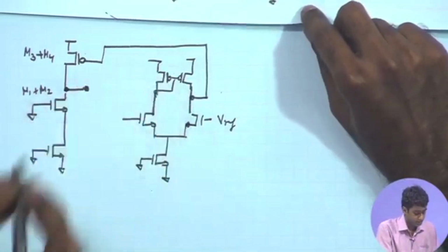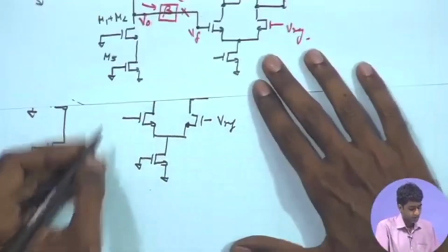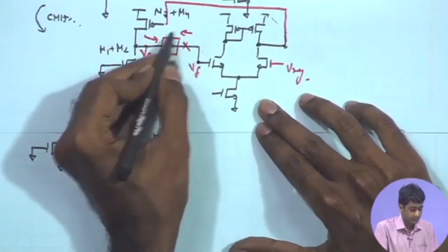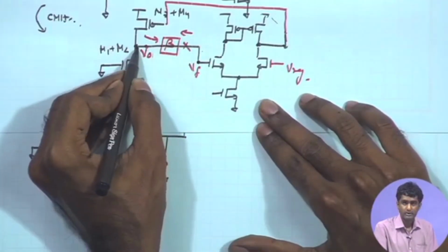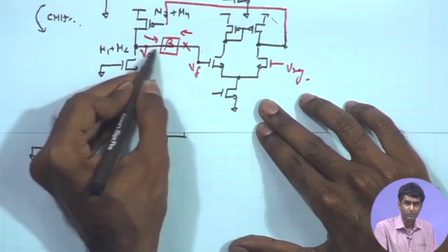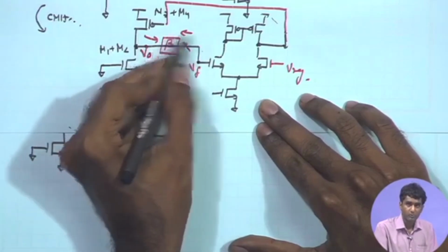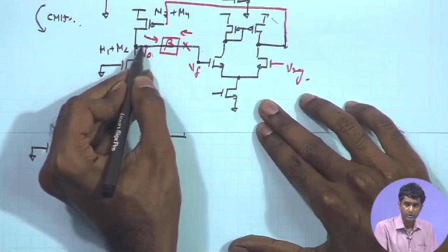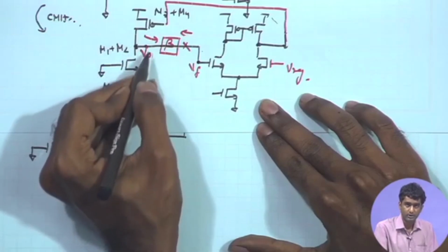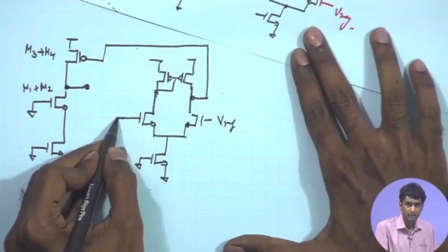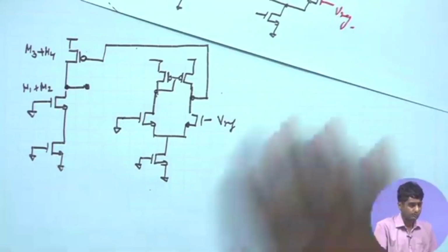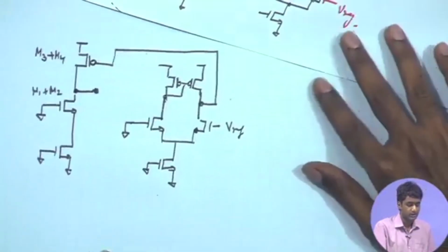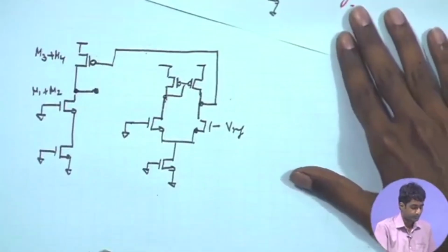Once again, while looking into the output port of the feedback network, the other terminal is a shunt connection. We are sampling the output voltage. So, looking into the output port of the feedback network, the input terminal was having a shunt connection. Therefore, we will just put an AC ground over here. So, this is an equivalent open loop circuit corresponding to the common mode feedback loop.